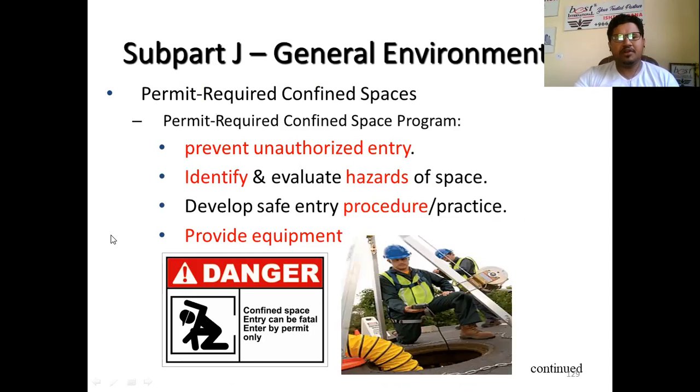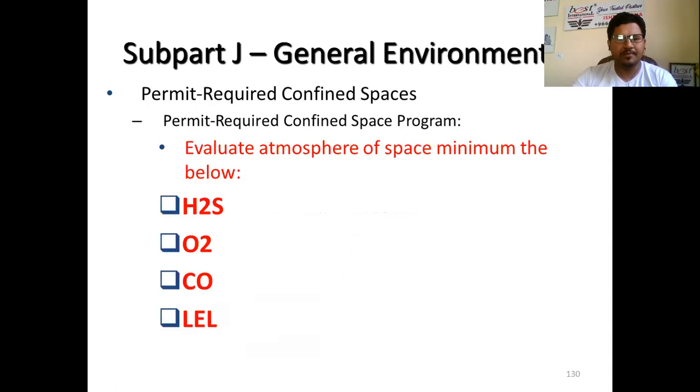And the purpose of the confined space permit is to prevent unauthorized entry, identify and evaluate hazards of the space, develop safe entry procedures, and provide equipment. All these steps relevant to confined space are mandatory. And most importantly, a minimum of 4 elements must be tested: H2S, oxygen level, carbon monoxide and LEL, the lower explosive limit.